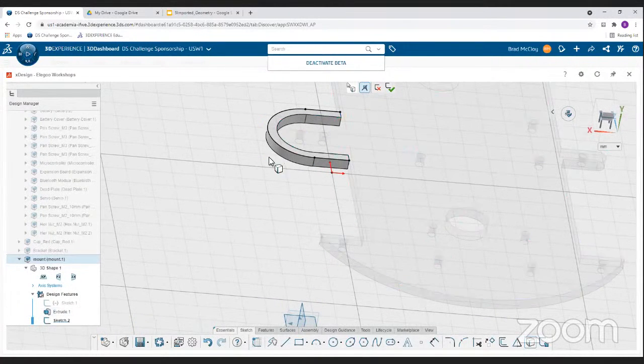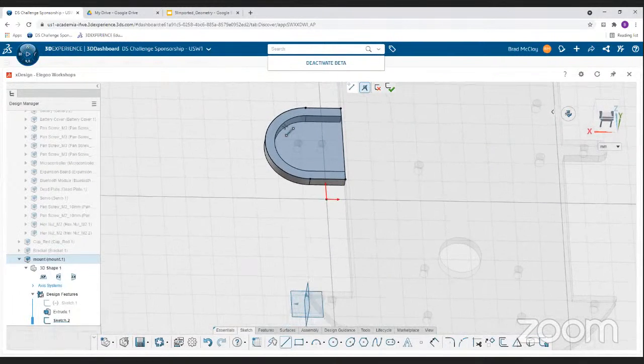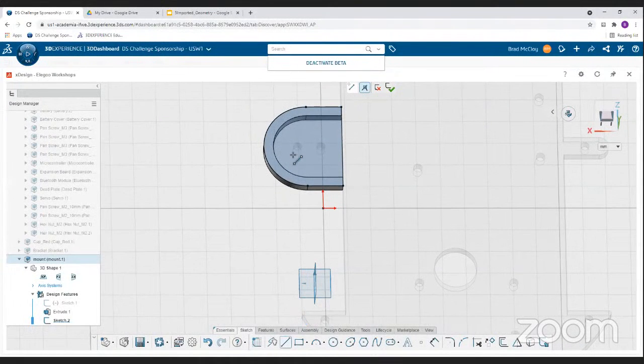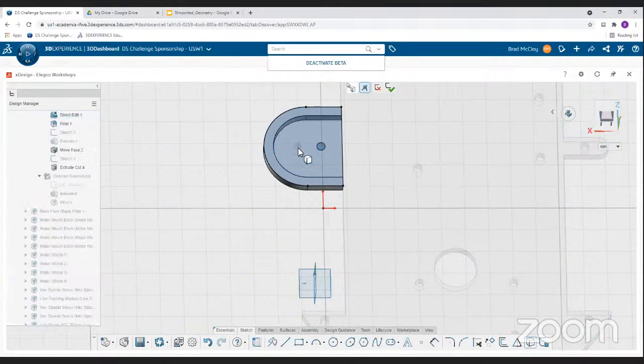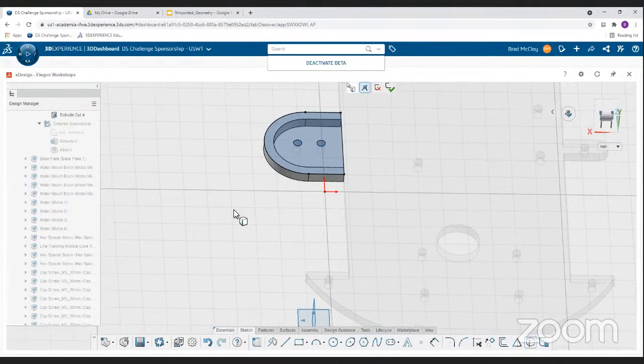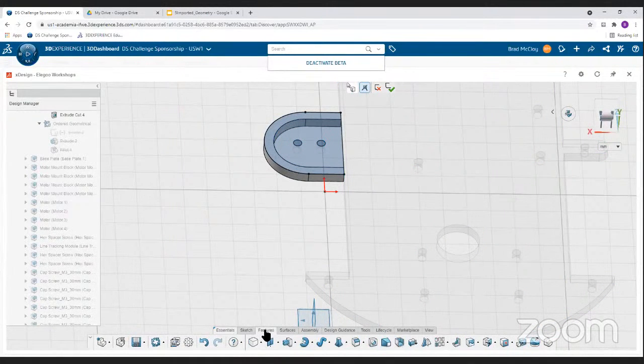So if I angle it a little bit, you can see what it is. Now, if we take a line and close off that last little bit, it turns shaded again. So we know we can actually do something with that now. But say if we wanted to have mounting holes for the screws too, we could convert entity of this and this. And now when we extrude that up to make it have some thickness, those screw holes won't extrude unless, of course, we want them to.